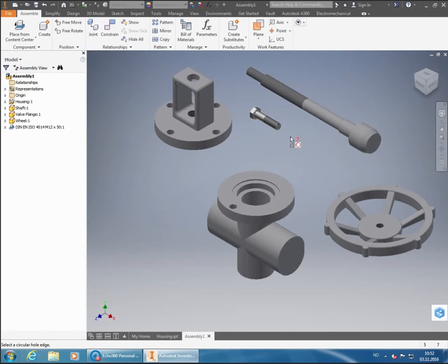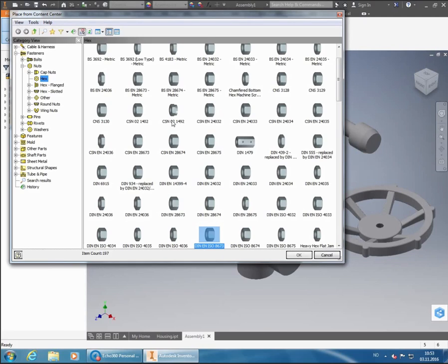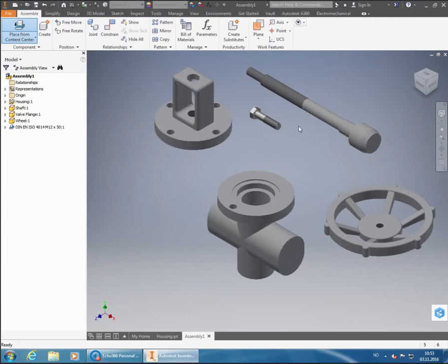And for this one, we're going to let Inventor automatically choose M12 for us. We're just going to hover it above the threaded part of our M12 bolt. And now it says that size is not available in that one. Let's see. It might be that I've chosen the incorrect 8673. Ah, that was the incorrect one. That was the M14 one, which was 8673.